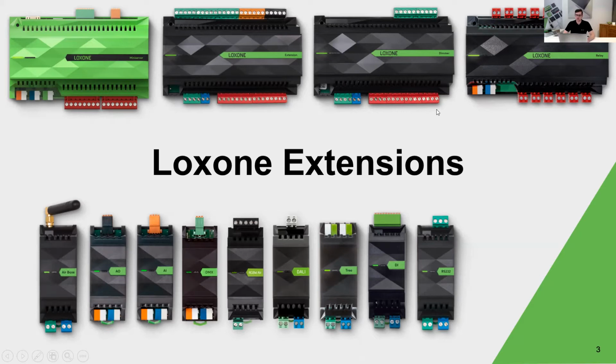Channels 2, 3 and 4 are rated to 210 watts. And that's their absolute rating, including inrush. So if you are doing mains LEDs, please account for the inrush current. That's the spike of current you get when you first start them up because the capacitor has to charge.